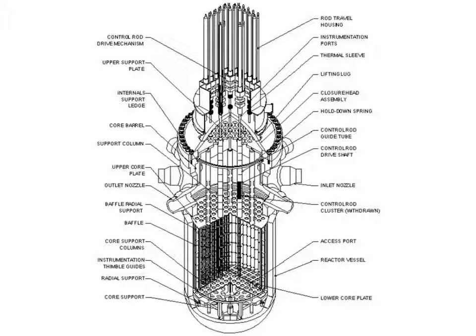The most important component of a nuclear power plant is the reactor core, contained in the reactor vessel. In a pressurized water reactor, the fuel rods contain uranium pellets enriched to roughly 5% uranium-235, contained in a cladding normally made of a zirconium alloy or stainless steel. These fuel rods are typically 4 to 5 meters in length and are grouped into bundles. These bundles are removed from the core at regular intervals to refuel the reactor.